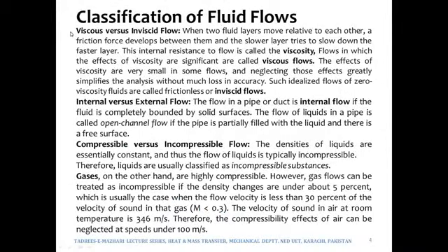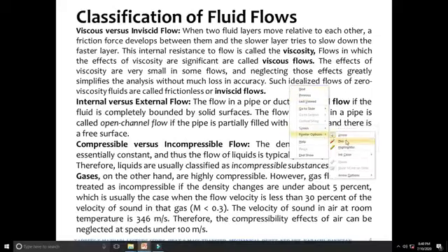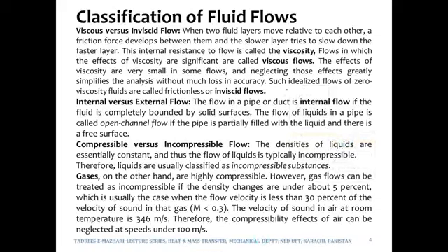The fluid flow may also be classified as either viscous or inviscid. Inviscid flow would be sort of an idealized flow of zero viscosity fluids. So if we are neglecting the viscosity, then that flow may be termed as inviscid flow, or if it is very small, so small that it can be neglected.